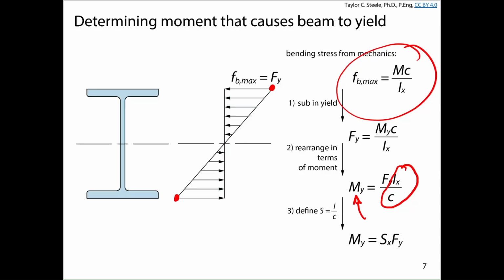Okay, so there might have been some fruitful discussions, and Katie had said you can probably apply more. Why do you think that is, Katie? Any ideas? Because this is just the yield strength. Mm-hmm. It hasn't reached its ultimate stress yet. So I think that means we could apply more. Like the steel's not gone, it's not fractured. Maybe we can apply some more. And maybe we can exceed the yield strain and start to go towards Fu or something like that, right? That's on the right track.